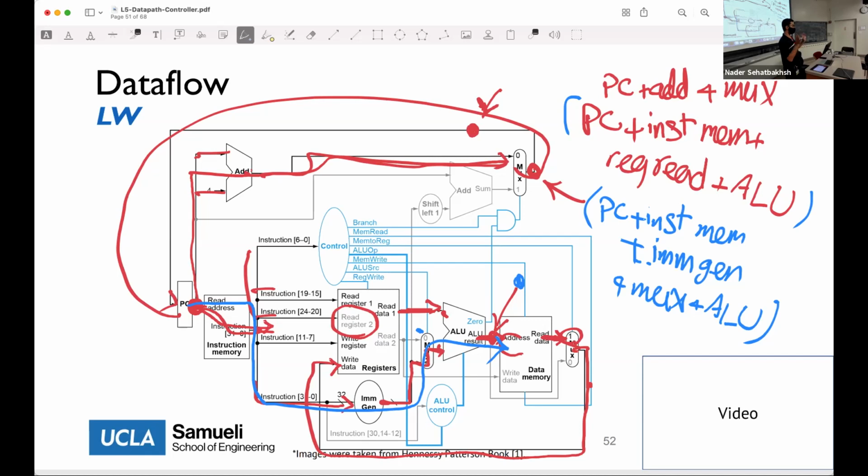The register file can read and write, and read and write are completely separate. They can happen at the same time. But keep an eye on the fact that this value is actually coming from this point. So reaching that point is much slower than reaching this point, right? The value that is valid for the register write comes much later than the value that is valid for the register read. Same register on the same cycle, exactly. Of course, either you just do the forwarding, saying same as I'm writing it here, or you just actually have the values.